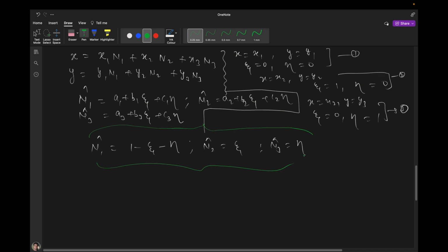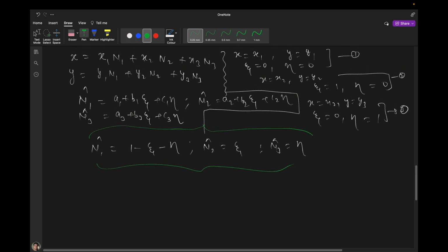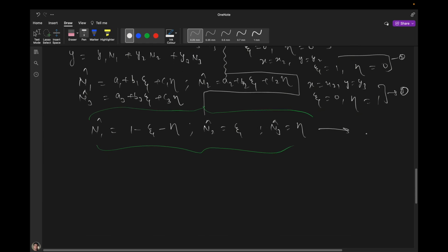We already saw that there are many different kinds of polynomial or bilinear shape functions, and that we can easily construct different kinds of shape functions by using Pascal's triangle also. Depending on the complexity of the problem, we can get different kinds of shape functions. But here it is a linear shape function, because there are two types of problems, H type FEA and P type FEA.